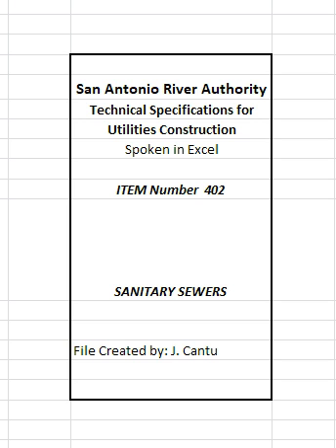A21.51/AWWA C151. Thickness or class shall be that required for laying condition type 4 or 5, in accordance with actual conditions at the site. Ductile iron pipe may be thickness designed in accordance with requirements of the latest revision of ANSI Standard A21.50/AWWA C150. Thickness design shall be based on standard laying conditions 4 or 5 in accordance with conditions at the site.